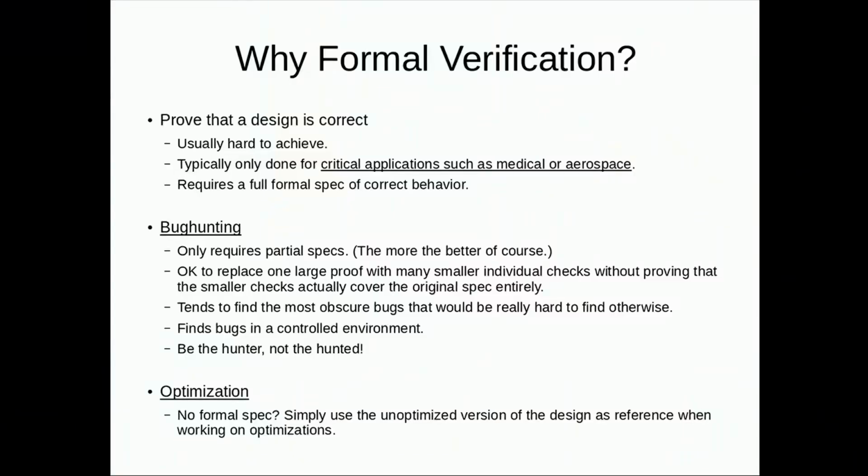And you only need to have a really good feeling that all these overlapping specifications cover the entire behavior of the circuit. Whereas when you would like to prove that the design is correct and you fracture it into individual small checks, then you have to have a second proof that proves that you haven't left any gaps with these partial specifications. There are cases where people do that and claim they do the first thing, but actually they don't, because these are questions that are left open. So this is just bug hunting.